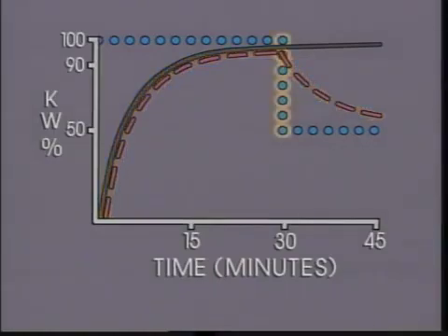For example, here the load decreased and the pusher arm moved down scale. Notice also, as indicated by the solid line, that the pointer remained at the maximum demand indicated before the load dropped. As with the mechanical demand register, the pointer will only be moved upscale if the demand increases beyond its previous maximum demand.